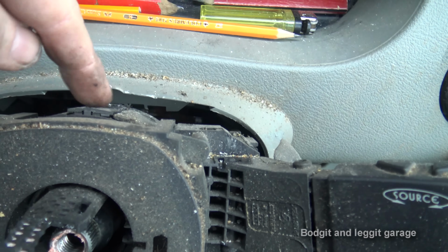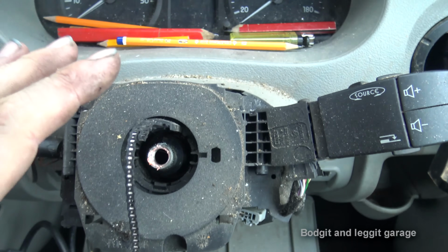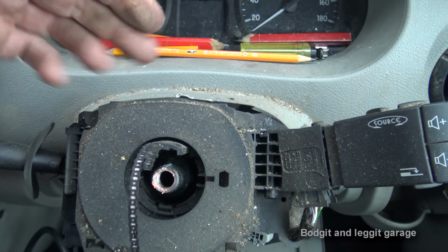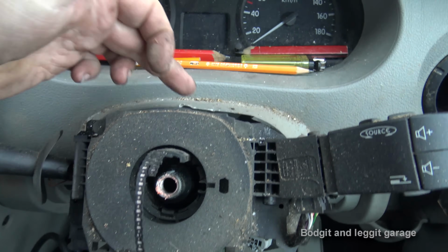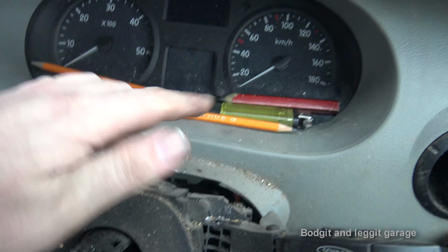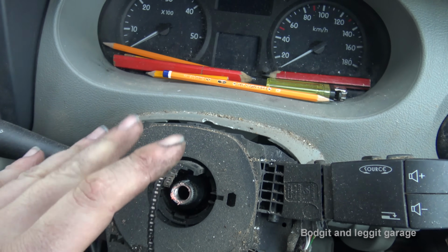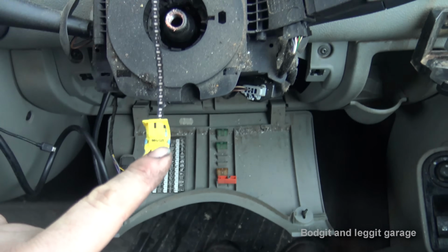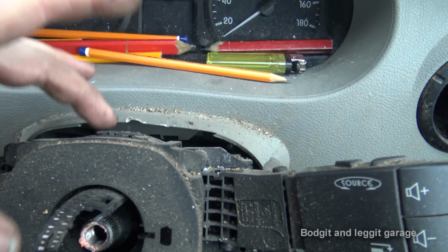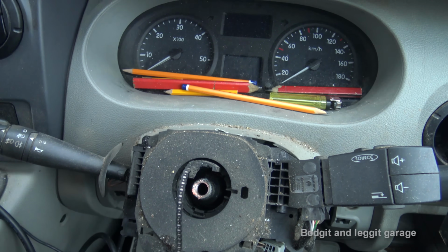But what we need to do is disconnect it down here, which again you just can't quite see. And then, is this loose or is it bolted? It'll be bolted somewhere. And then we can actually test the clock spring. So what I'm going to do next is take out the wire behind the clock spring and put my resistor in. If the light goes off, then we know there is a problem internally in the clock spring, because we have tested from here all the way back and it hasn't worked. So if we test from here back, the only thing in the middle is the clock spring. So it really is as simple as that.